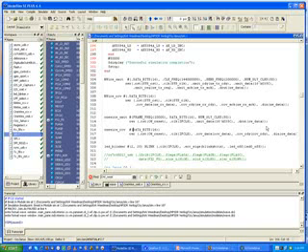I'm just physically connecting these two together, like wiring them up. Then there are some other signals, like the received data is ready, which I can use elsewhere in the simulation. I'll show you that in a minute. And the actual received data. Then I feed it a clock, my local clock, this IF clock, and then reset. Both of them use the same reset.